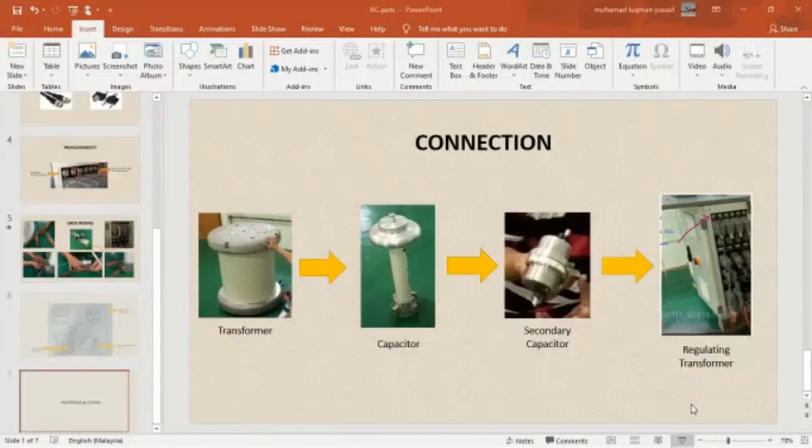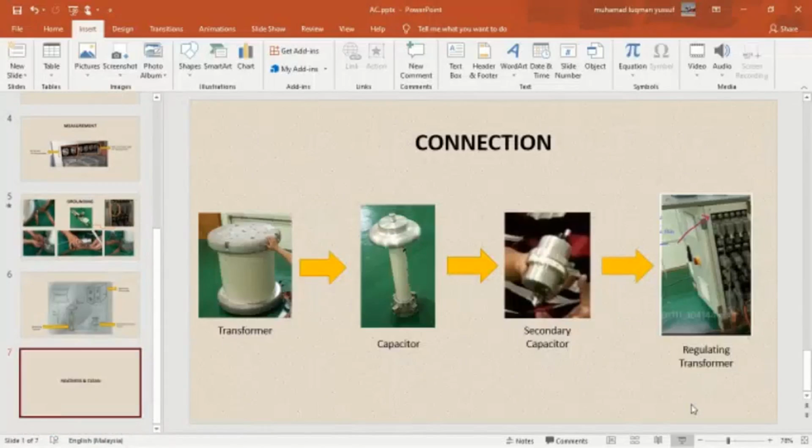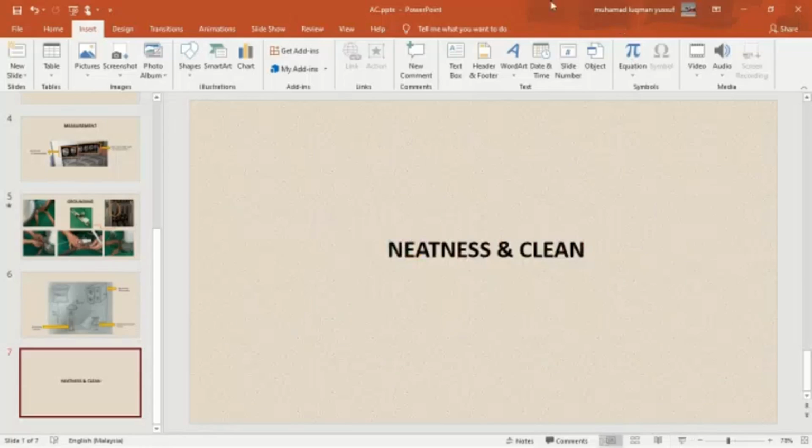Fourth one is take regular air samples. Air samples help ensure a clean room environment is meeting specifications. Typically, either air samplers or settle plates are used to gauge whether any contamination has occurred.